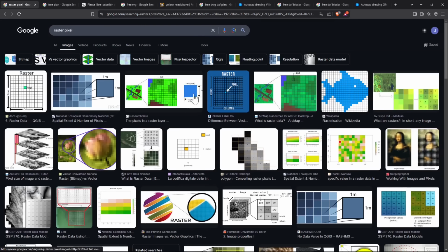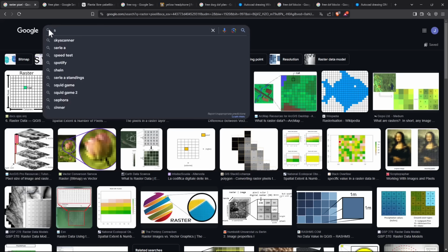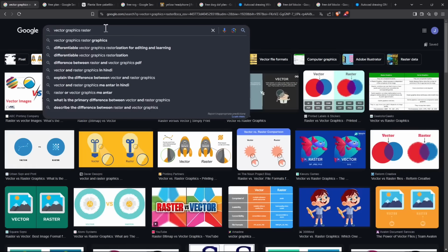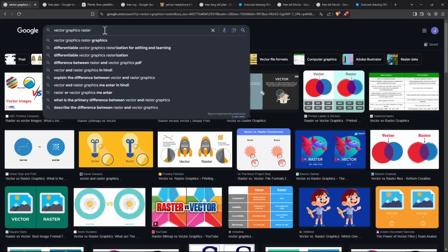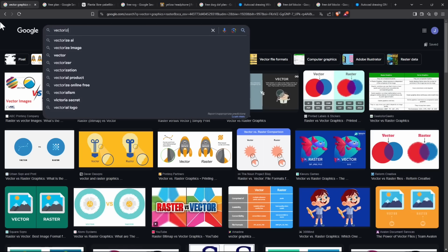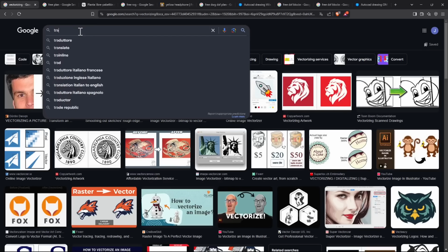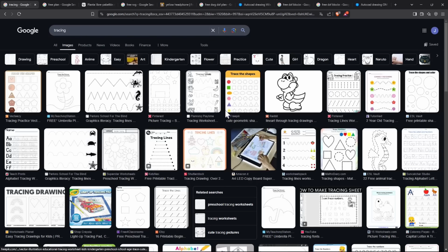Now, unfortunately, this is not really handy in 3D, so we need to convert this into scalable vector graphics, or vector graphics more in general. And we can see the difference. Vector graphics are essentially neat and defined, and you can scale them, upsize, downsize, anytime. They will never lose quality. And you can also use them for 3D purposes or for other graphic design purposes. So there is a process which is called vectorizing or tracing, and it's basically tracing the lines in the pixel image and making them vectors.